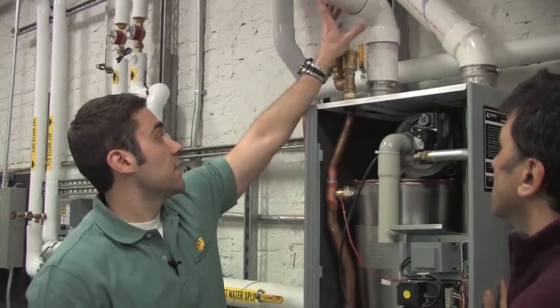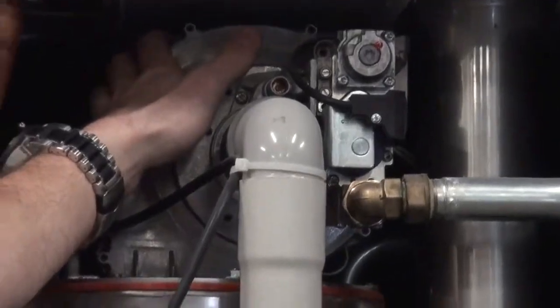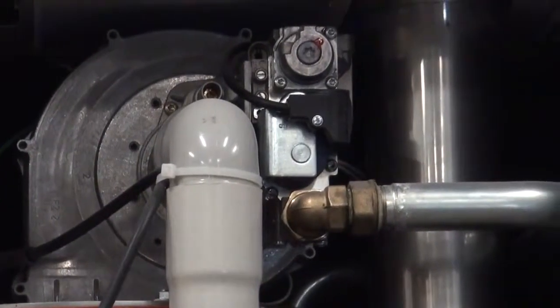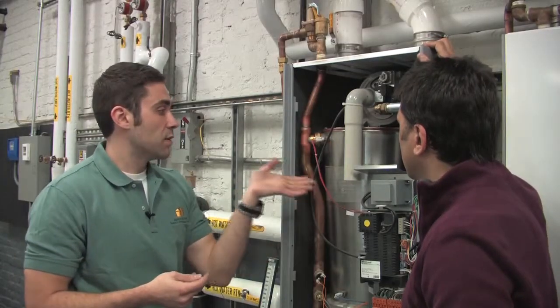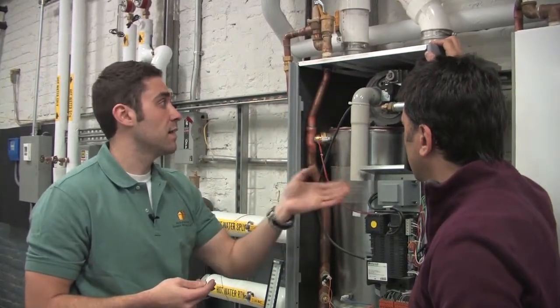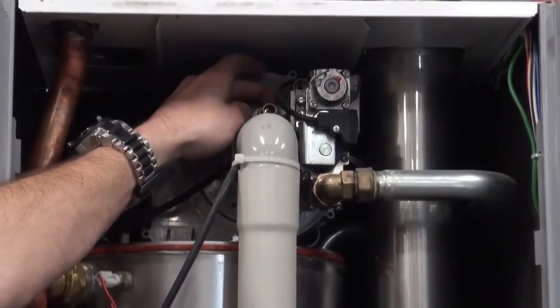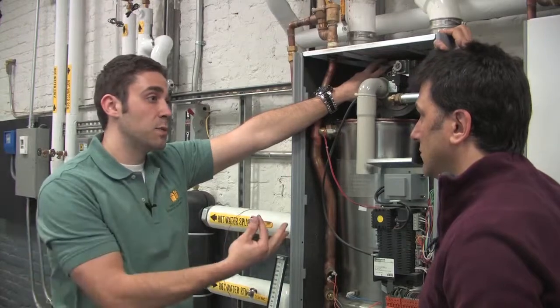So the air is coming in down through this pipe and it gets into this compartment. Inside this compartment, we have a fan in the back, similar to the inducer motor we saw on the furnace. Same design, it's pulling air in and regulating the amount of combustion. So here's the inlet to that. The air from the outside works its way into the compartment and gets into the inlet of the fan. As the fan pulls air through, we have a negative pressure gas valve inside here. And the way that's designed is the faster this fan spins, the more gas we pull in for combustion.